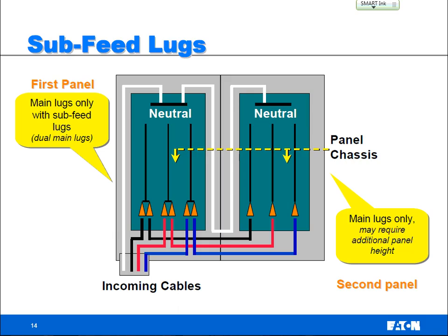A lot of times the existing facilities or the industrial facilities, they don't worry so much. Space is more important, so they'll take full advantage of using 84. A lot of times 54 or 60 circuits seems to be a good break number where they'll put that all together into one panel board tub. But on new construction, I'm still seeing a lot of 42 circuits.